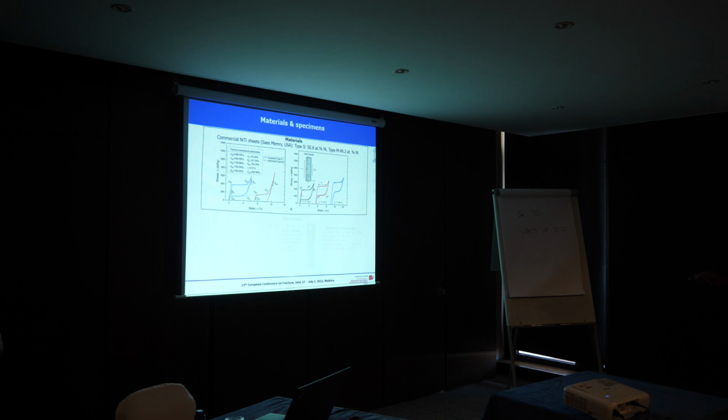The critical stress for stress-induced transformation increases with increasing temperature. And this is exactly what we have studied. To this aim, we used single-edge crack samples obtained from nickel titanium sheets with thickness 0.5 millimeters for both fracture and fatigue experiments.